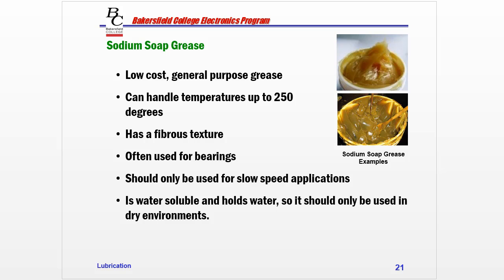So that would be a big no-no, because as the wheels that are on the trailer are under the water, that grease is going to get washed out of those bearings. Now, you could back it in one time quickly, launch your boat and come out, and you're going to have grease in there. It's not just going to come pouring out, but over time and swishing in and out of that boat ramp, you're going to run all that grease out of your bearings.